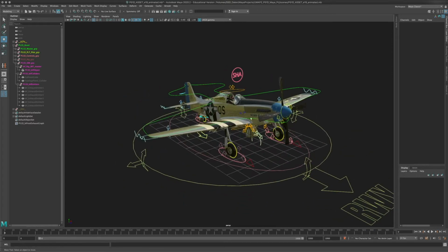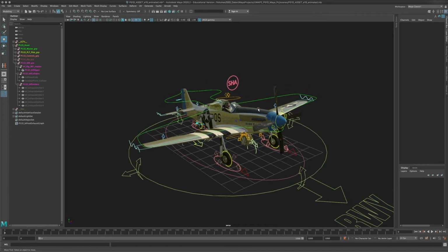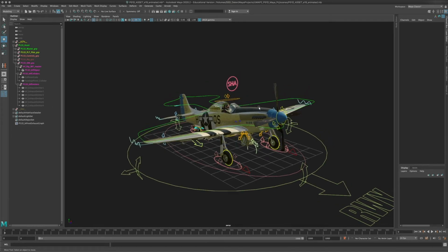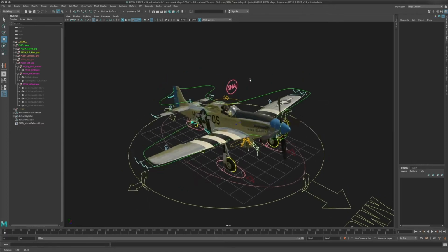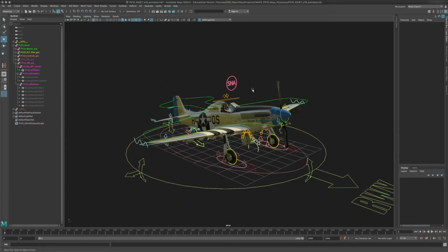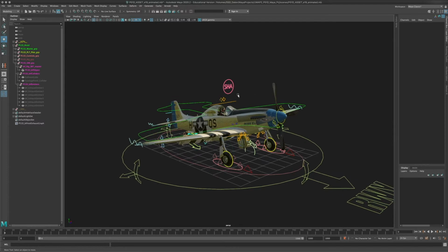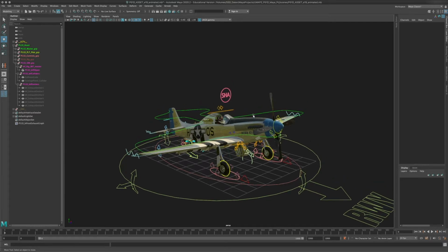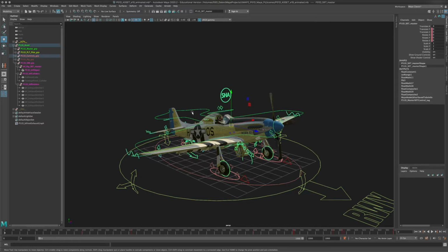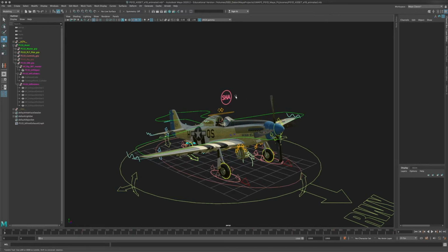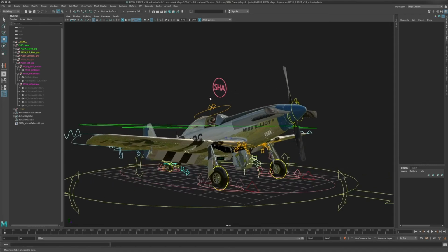So in this case, I don't ever really need to export the thing, but if I wanted to render with Arnold on the GPU, I'd have to export to a VDB anyway, and can't directly render the BIF object, which is a bit annoying really, because maybe they could just do the translation to VDB on the fly for that, or implement the BIF object on the GPU as well. I know it's not that easy, so I do understand why it can't be rendered currently, but it would be a lot faster than on the CPU. So the smoke sim will have to render on the CPU, at least if you're not outputting to VDB, which you could.